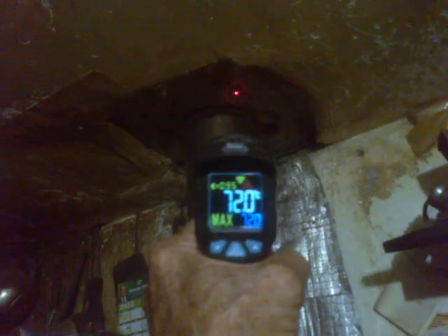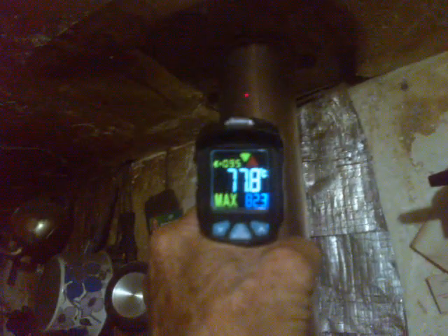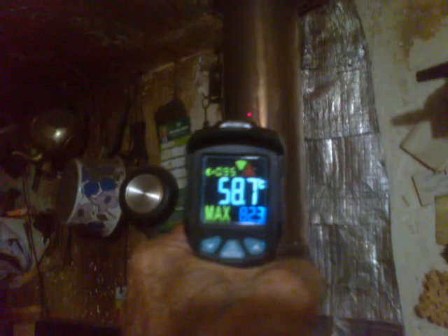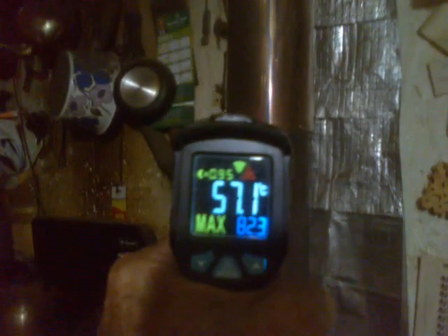63 degrees metal at the ceiling, 65 degrees the outside of the air-cooled flue, getting cooler as we come down. Any kind of a discontinuity tends to give you a raised temperature. So when we come down here to an old corrosion band, it's going to go up. Yep, look at that, see? We come back down to there, it drops again.